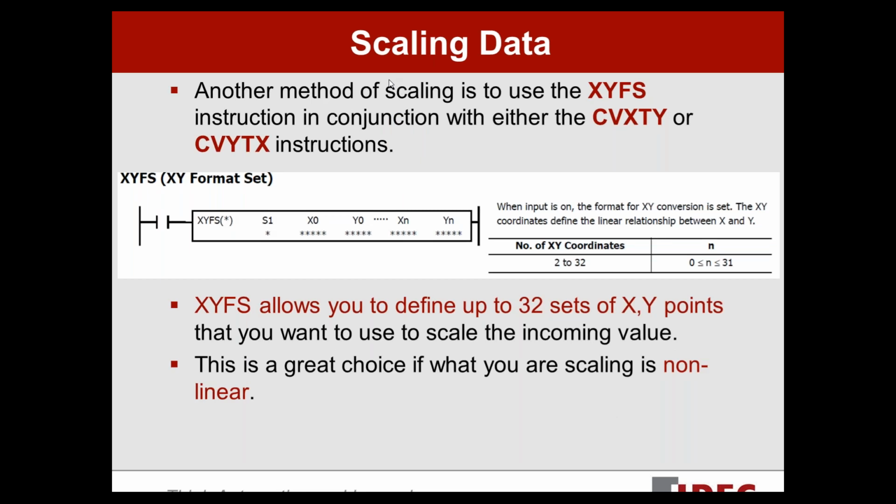Okay, another way that you can scale data is by using the XYFS, which stands for XY format set instruction, in conjunction with either the CVXTY, which is convert X values into Y values, or the CVYTX instruction, which is the convert Y values into X. Okay, so XYFS can be used with either of those two convert instructions.